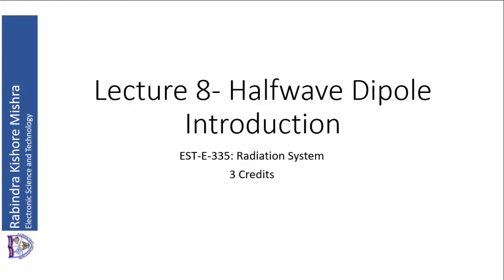This is called a half wave dipole antenna because this half wavelength of folded transmission line can be analyzed by considering it as a combination of many Hertzian dipoles along the length. So this is like a dipole which contains many Hertzian dipoles.